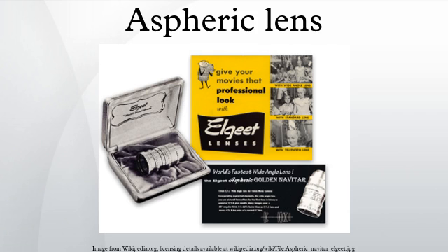An aspheric lens or asphere is a lens whose surface profiles are not portions of a sphere or cylinder. In photography, a lens assembly that includes an aspheric element is often called an aspherical lens. The asphere's more complex surface profile can reduce or eliminate spherical aberration and also reduce other optical aberrations such as astigmatism, compared to a simple lens.